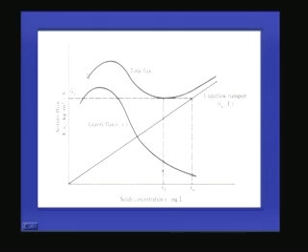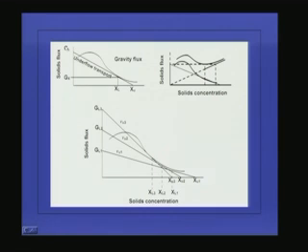Now we will see how the total flux will look. This is the flux due to underflow transport, because Vu remains constant and Xi keeps on increasing, so you get a straight line like this, and this is the gravity flux. If you take gravity flux plus underflow transport, you get this point here, corresponding to this distance plus this height. That is the total flux, so we get a total flux curve like this. How can we use this data for the design of a secondary sedimentation tank?